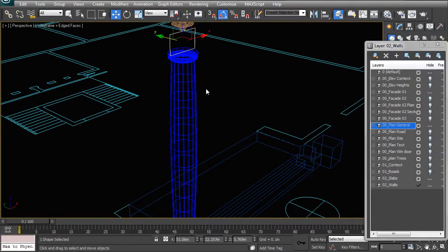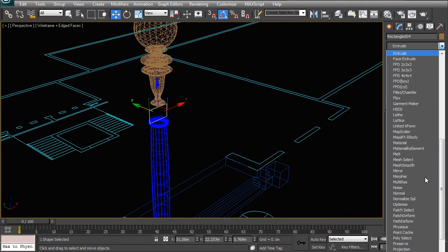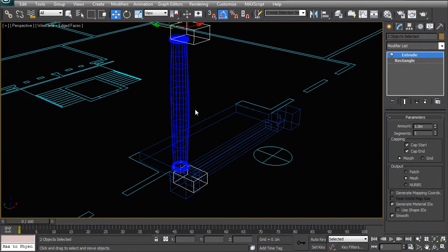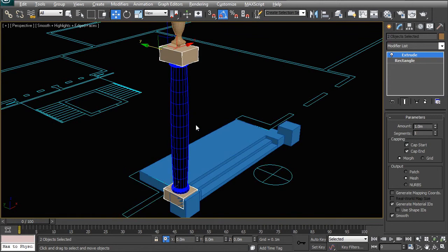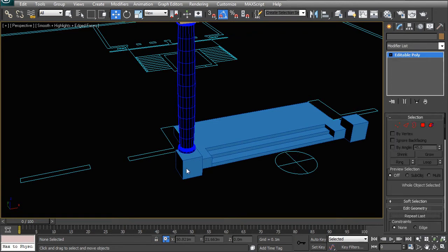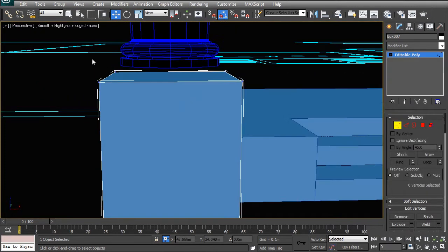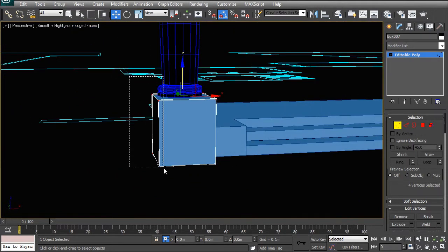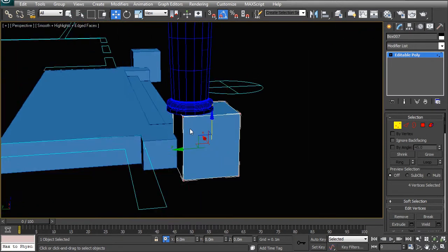And these rectangles that we created, we want to extrude them. So if I just go across EXT enter, and I will use 1 meter just for the time being, and I'll move it back by 0.5 meter just so that it can be centered. This one actually here we can delete since it is standing on this base, and then we can go and adjust this base to fit the height of the column. So here you can either do it very geometrically using numbers or just by eye, looking at your elevation. So I'm going to just drag this back slightly.